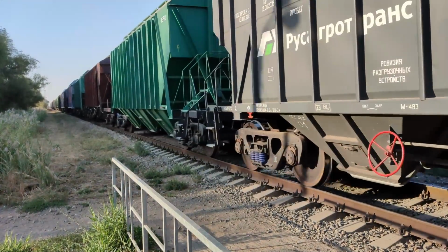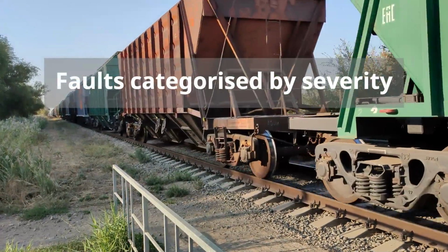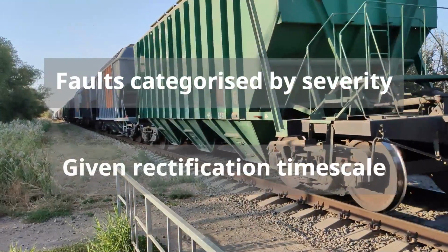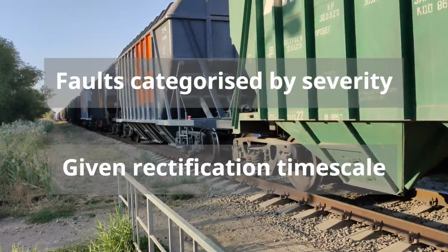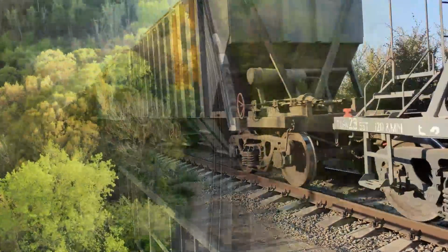After the train has recorded all these geometry faults, they are categorized by severity and given a time frame in which they must be fixed. They are then sent to the maintenance teams for them to plan rectification. There we have an introduction to track geometry.